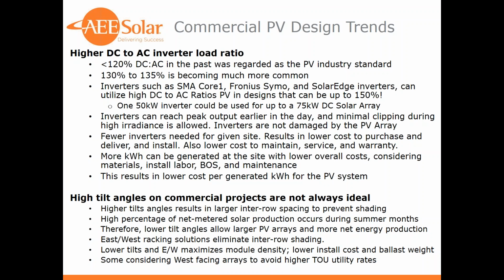Some are also considering facing arrays to the southwest or even to the west in high time of use states and utility districts. The time of use rates are much higher in the afternoon, so there might be some consideration to face arrays either southwest or west, as opposed to due south, if there's a choice there.